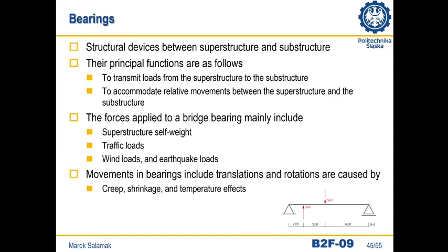Another essential component is the bearing, which, unlike other devices shown today, is also used to transfer loads. You know them from mechanics, most often as fixed or movable bearings. They are a device between spans and supports. Their primary function is the transfer of loads in the form of reactions from spans to supports.